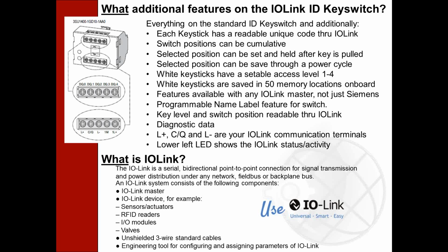So the key switch also has a programmable name label feature for the switch itself. In other words, when you get into your IO Link and you're looking at your master, some of the masters have multiple positions. The master we're working with here has 4 IO Link connections. Each of those switches, you can put a name label in, an electronic name that you can plug into that unit. You program it in, and then when you get back online with it, you can verify who you're talking with, that particular switch, just to make sure you're not working with the wrong switch if you're working with multiples of these.